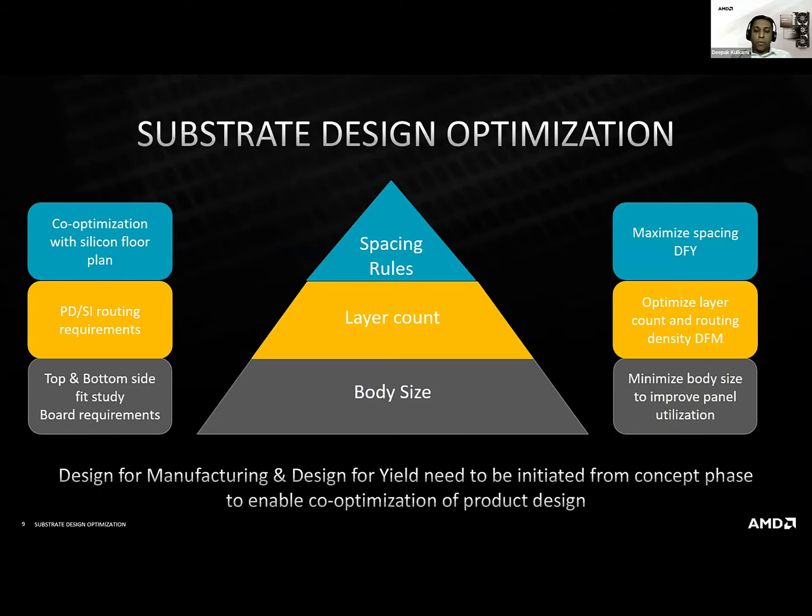And I think it goes back to this topic that I was talking about with regards to modularity. So if you are looking at this purely from a yield perspective, you could design a set of equations that would say beyond this die size, there is net benefit in splitting because the cost associated with the chiplet architecture is lower than the yield loss of the monolithic SoC that you're going to build.